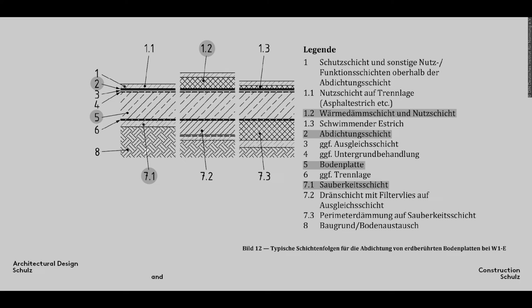In the absence of vadose or groundwater, and where the soil on which the building is erected has a reasonable load-bearing capacity, the sequence of layers from the bottom up is generally as follows: blinding layer, reinforced concrete slab, damp-proof membrane, insulation, screed, and floor covering.